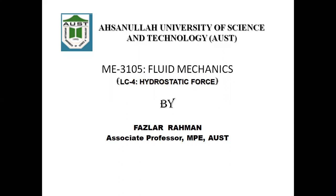In that case, you need to install two mechanical pressure gauges in two locations, right? And also we learned how we can figure out the pressure difference between 2 points in a pipe or in between two separate tanks by using a manometer, right? If you have two tanks at a certain distance, say 2 feet or 3 feet, you need to add two mechanical pressure gauges to figure out the difference, right?